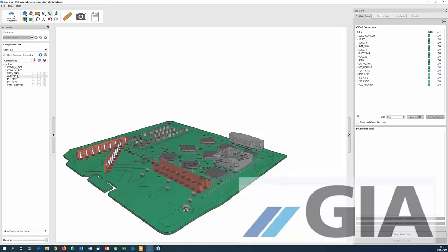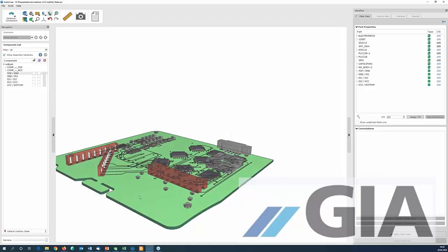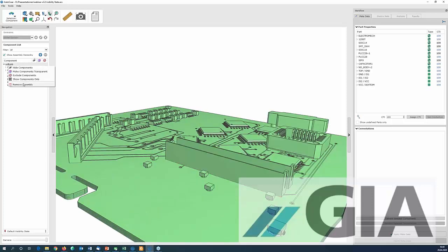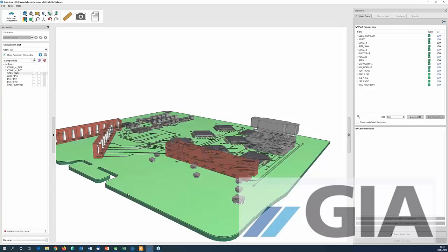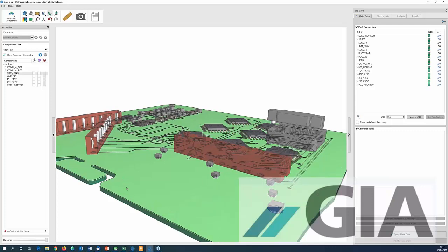Also note that we cannot remove the individual layers of a PCB. The remove function is missing because the PCB can only be removed as a whole assembly, but not individual layers, because they are already pre-processed in one single solid body, which cannot be separated anymore. If you don't want to have certain layers, you can already leave them out in the import mask of a PCB.